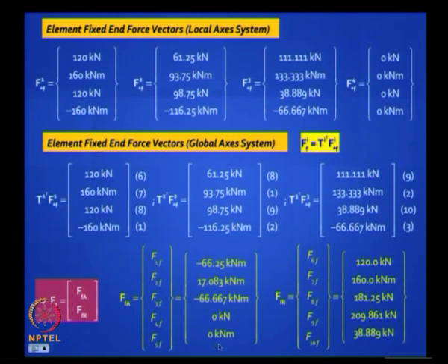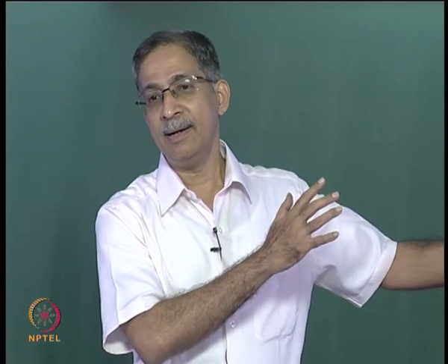Some of them will remain with zeros. This is something that is accumulated in the active coordinates, so it will operate as a load, but you must oppose it, you must put a negative sign. This is coming in a restraint coordinate, so just keep it there and add it to your reactions later.